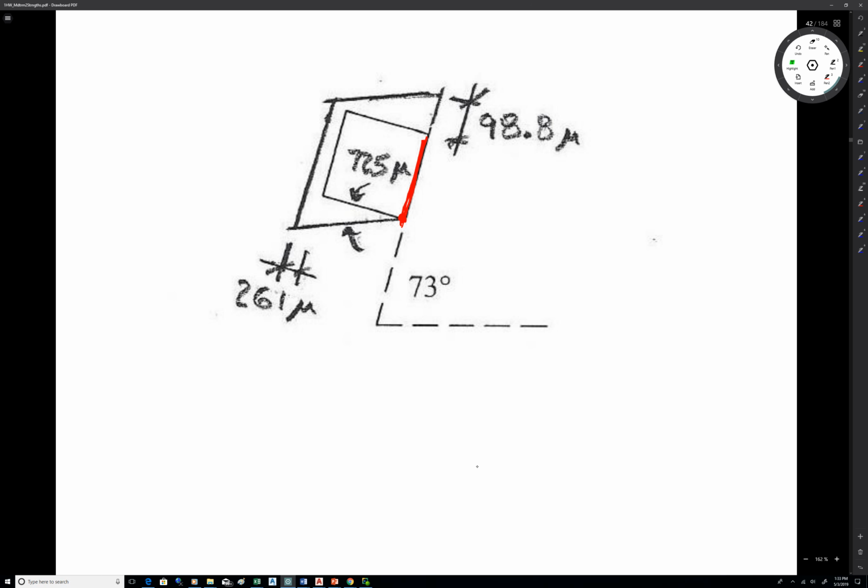So this is more of a schematic sketch that you can dimension. So epsilon x1 extends this corner out 99 times 10 to the minus 6. Epsilon y1 would take that corner and extend it out to 61 times 10 to the minus 6. And then the shear strain at that angle is negative, so that original right angle gets bigger, and we show all that deformation happening on one side so we can dimension it, okay? So that's what the sketch would look like.